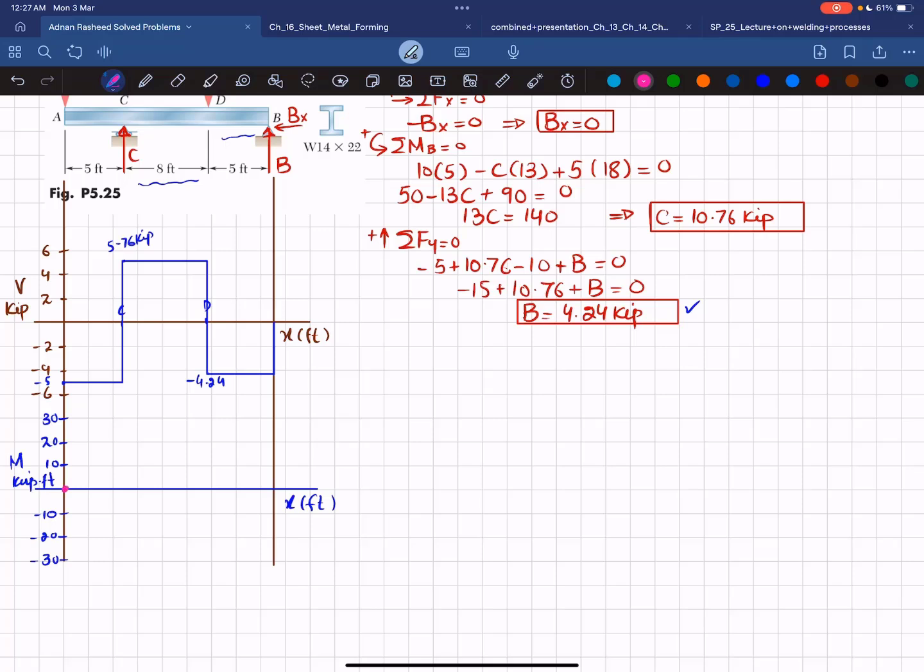Now we can see that area under the shear force diagram will give you bending moment. So first area under the shear force diagram will give you bending moment. Let me call this area A1. So I will write here A1 is equal to minus 5 multiplied by the length over which it extends, x is 5. So it will give you minus 25. So at point C, C is this point. So this will be minus 25, which will be like this. This is minus 25. And you can see that shear force is a horizontal line and this A1 area is negative. So bending moment will be a 1 degree line and slope will be decreasing. So it will be like this. I will join these 2 points using a straight line.